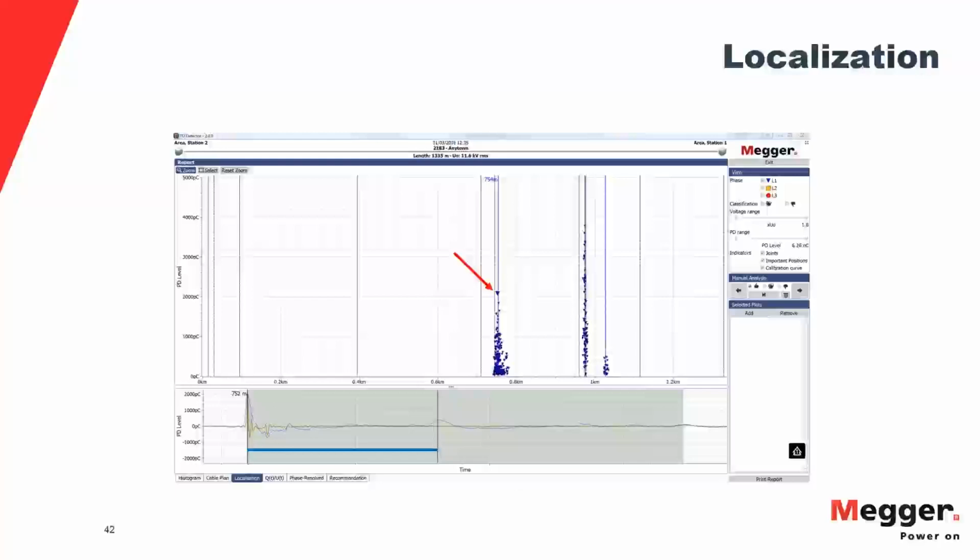The receiver picks up this initial pulse, and that's when it starts the timer, and it sits there counting and waiting for this pulse to arrive. Once that pulse arrives, it stops the timer, and it can calculate the time between the two pulses, and if we know the speed those pulses were traveling, we can calculate the distance. Of course, in this example, I slowed it down so you guys can see. It doesn't really stop at the end. These signals don't stop. They flow smoothly through, but I slowed it down so you guys could follow along.